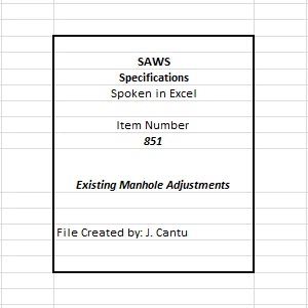3. Existing manhole rings and covers which are determined by the inspector to be in an unacceptable condition will be removed and replaced with new rings and covers. 4. If the cone section is removed, the contractor is to upgrade it to a 30-inch opening as required by 30 TAC 217, at no cost to SAWS. 5. All manhole openings upgraded to 30 inches shall then be subjected to all provisions of specification item number 855, existing manhole reconstruction, except for the manhole ring and cover provisions, which are specified under specification item number 852, sanitary sewer manholes.